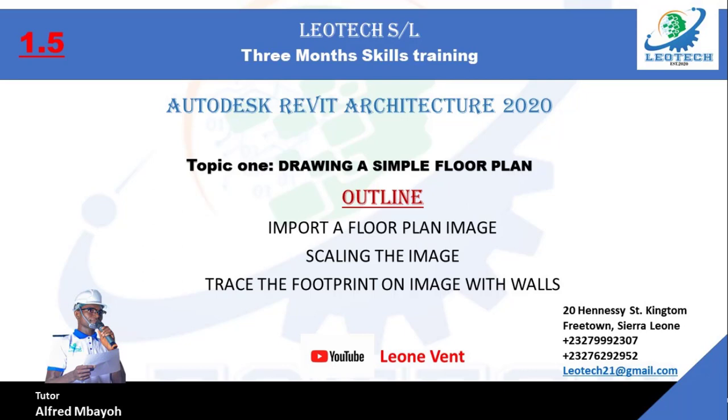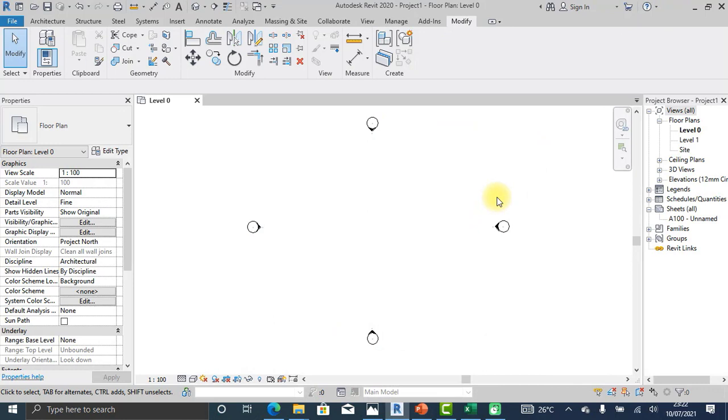Today we are starting off with drawing a new plan, a floor plan. So we are importing an image, a floor plan image that I downloaded. We are importing it in the Revit Architecture work environment, and then we are scaling it to fit the workspace, and then we are tracing the footprint on that image with walls. So let us jump into the Revit Architecture work environment.